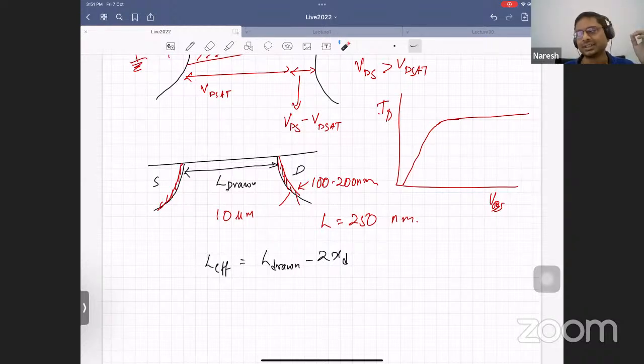Generally what happens is, when we study semiconductor devices, we write these nice equations, ID is equal to mu Cox W by L into (VGS minus VT) whole square and all that. That works in the olden times, but nowadays things are so complicated that you actually model all these things with what are known as SPICE simulators, BSIM models. Those are semi-empirical models with some amount of physics, but a lot of empirical parameters. You require about 200 parameters to describe a MOSFET nowadays. So it's a pretty intense thing.